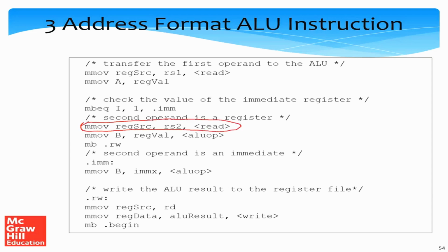So recall that two things are being done here. First, we are setting the contents of reg source to the contents of rs2. That is one thing. In parallel, I remind you, in parallel, simultaneously, concurrently, we are also accessing the register file. Why are we doing that? Because the command is being sent via the bus, via the args field of the bus, to the register file to either read or write. In this case, it is read. Doesn't matter, it can be read or write.